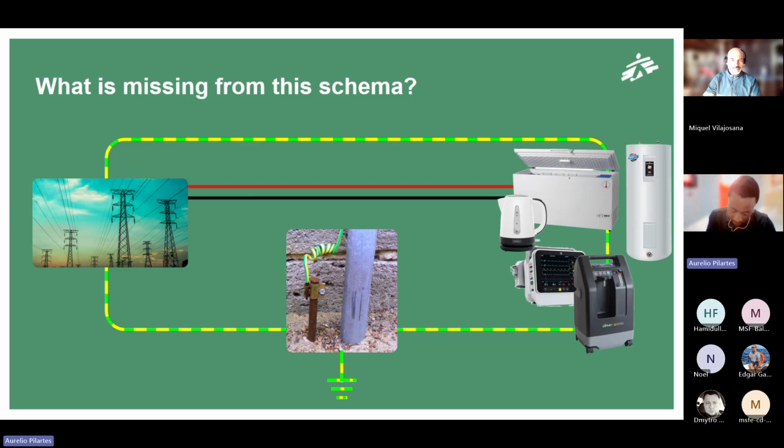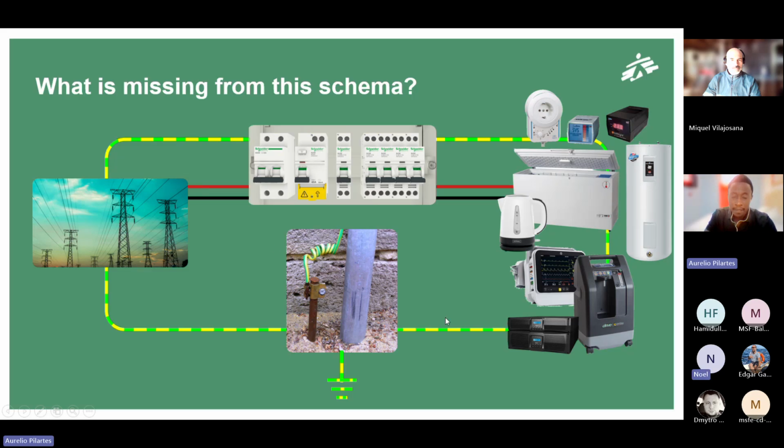And finally, also, and one of the main importance, MCB. We mentioned RCCB, we did not mention MCB. So MCB is also to protect against short circuits and overloads. So as you can see here are our protection devices.